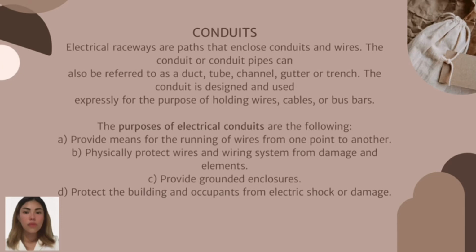The purposes of electrical conduits are the following. A. Provide means for the running of wires from one point to another. Second, physically protect wires and wiring system from damage and elements. Third, provide grounded enclosures. And lastly, protect the building and occupants from electric shock or damage.